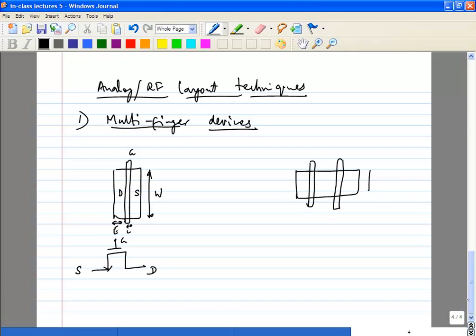and you can also draw this transistor like this, where let's say we go to a 2-finger transistor. This is W over 2. This is again E. So that E does not change. Okay, so you have some parasitic capacitance on the drain and the source, and you typically want to minimize these parasitic capacitances. So what you want to do is keep the drain and source diffusion areas as small as possible. What that means is you just want to make it wide enough such that you can put in some metal contacts. And that's pretty much as wide as you want to make it.